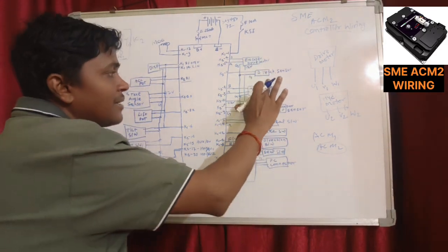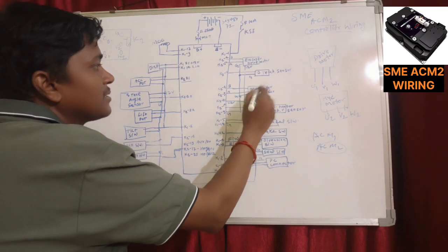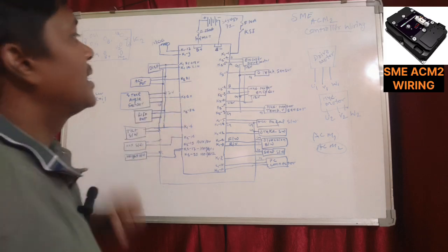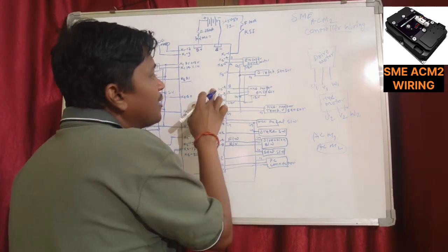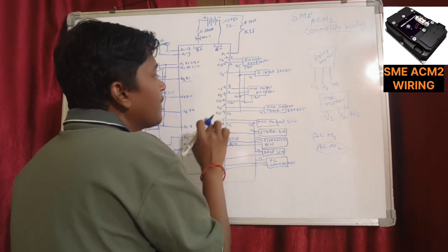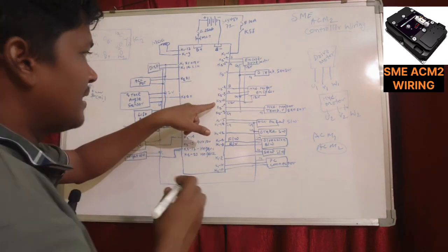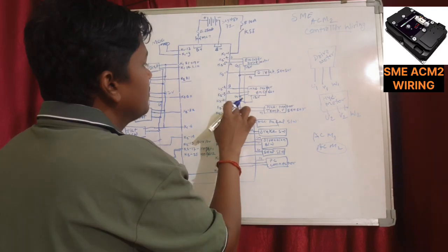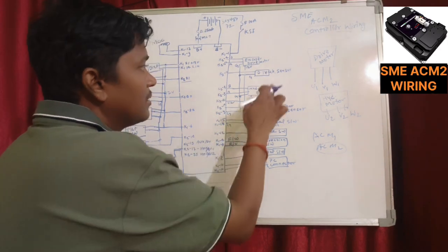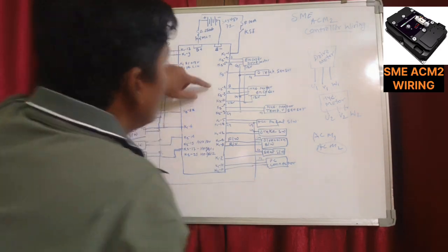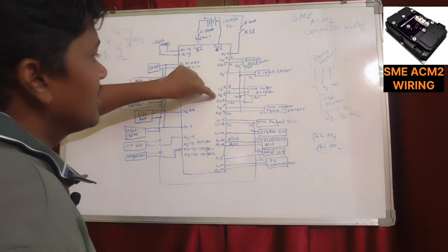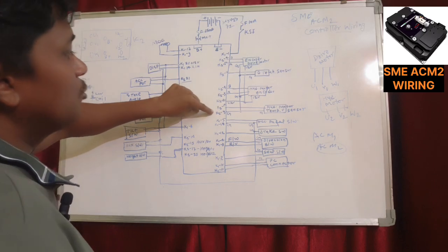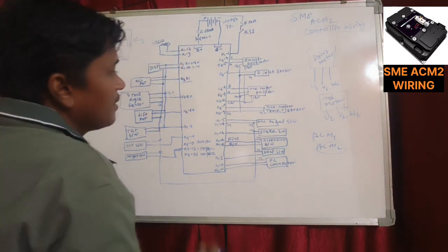Again I am coming to another encoder and another temperature sensor, which is required to connect with the hydraulic motor. This encoder will be connected: channel B will be K22, channel A will be K23, and ground will be K9. Sorry, ground will be K29, and another positive volt will be K121. See, this hydraulic motor encoder: K22 channel B, K23 channel A, K221 positive 12 volt, and K29 will be negative ground.